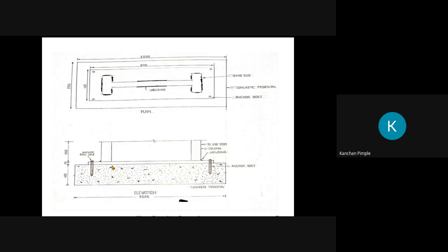Then this plate is known as the column base. In this case, as per loading, your column base may be a gusseted slab base or a moment resisting base. If we provide a stepped column, then this base is a moment resisting base. So first you have to design that, and the size of this base is just here 870 by 400. So this dimension, first we go for this. Okay, and this is the moment resisting base. No gusseted base is there, only plate is there, as the load coming on that column is heavy.